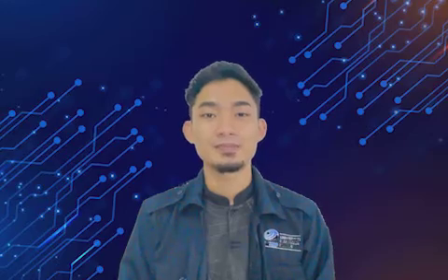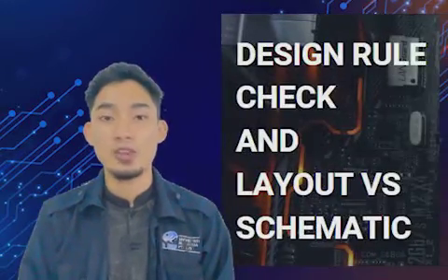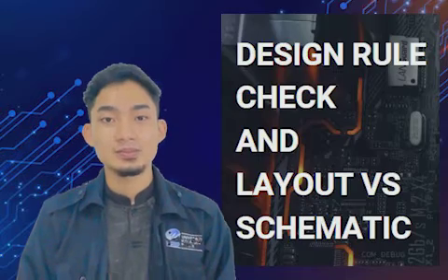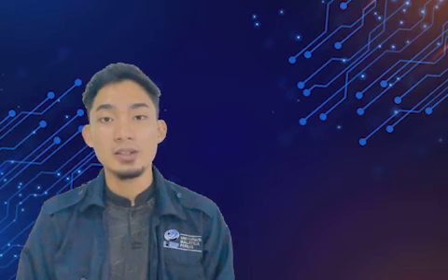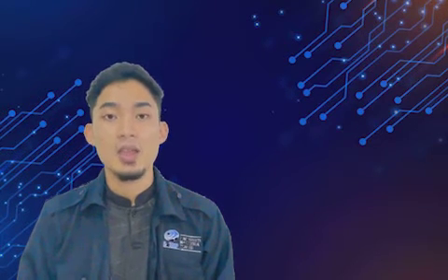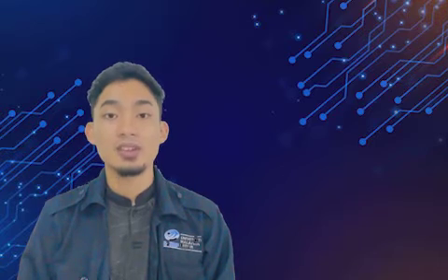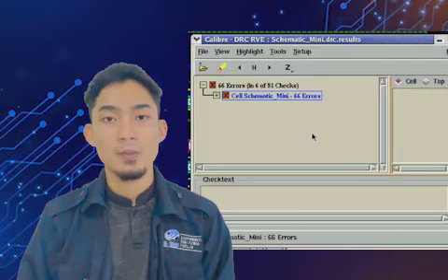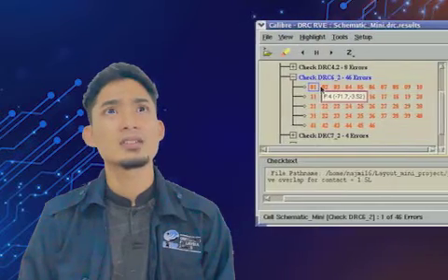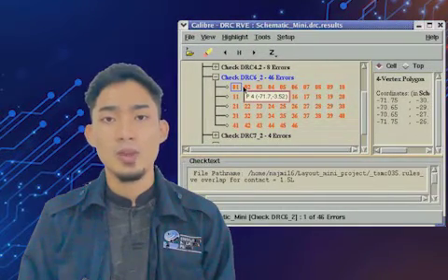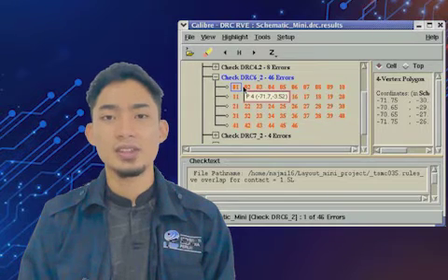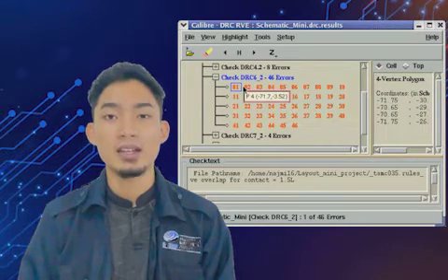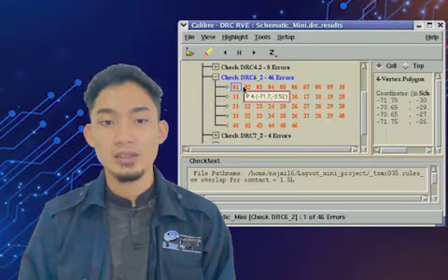Alright, thank you. I will explain about the DRC and Fakrul will explain about the LVS. DRC is required for us to check whether the layout is correct or not. After we ran the DRC for the first time, we received a total of about 16 errors. The layout of our mini project commonly had errors at active and contact to active. The specification of the distance needs to be at least 1.5 lambda, and our layout was 1 lambda.